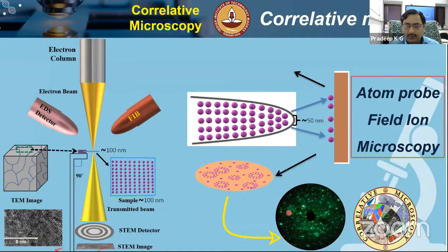And at some point, if you start evaporating the species also together, we'll see that this ring structure starts shrinking. That means it starts losing atoms one by one as the atoms get evaporated. So the more these rings shrink and disappear, one can even measure the number of circles that are disappearing to measure the nanocrystalline grain size.